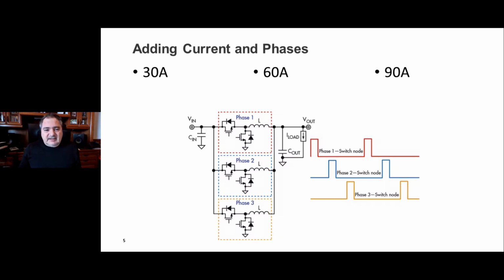So 9 phases, that's essentially 9 additional permutations of power testing that we have to do. Remember, the power management solution is running at a completely different clock domain than the chip, right? They're not synchronized to each other.